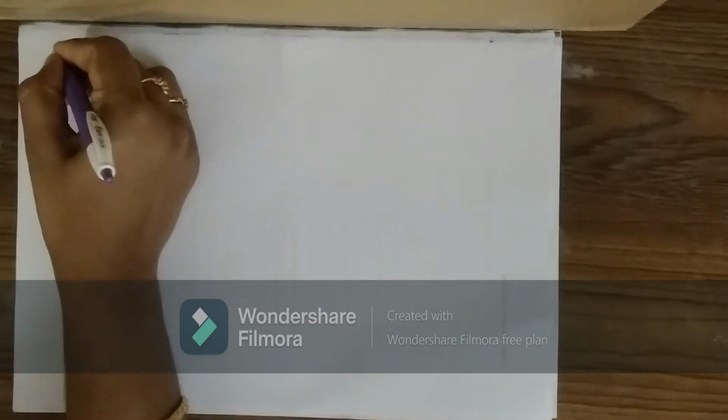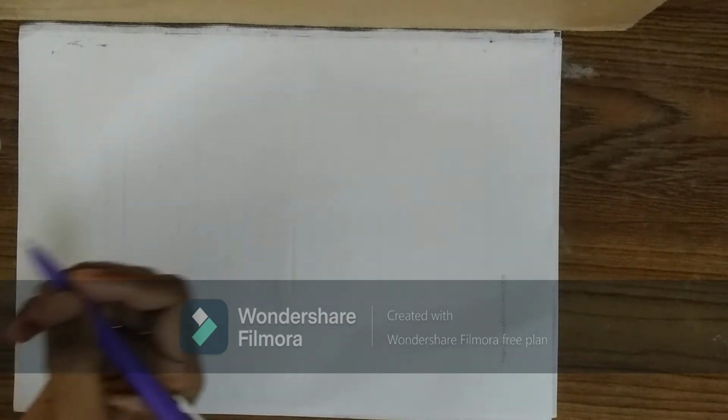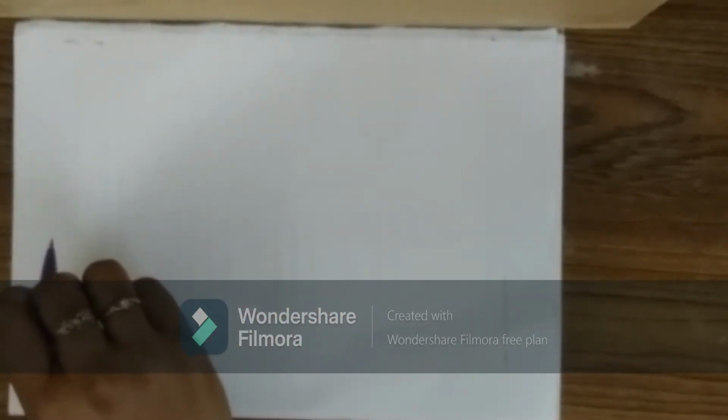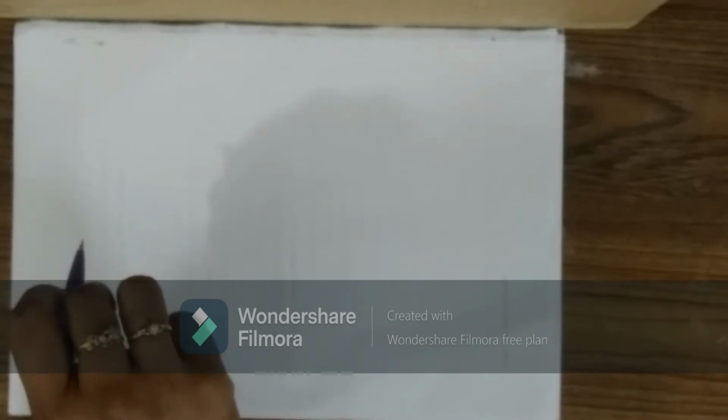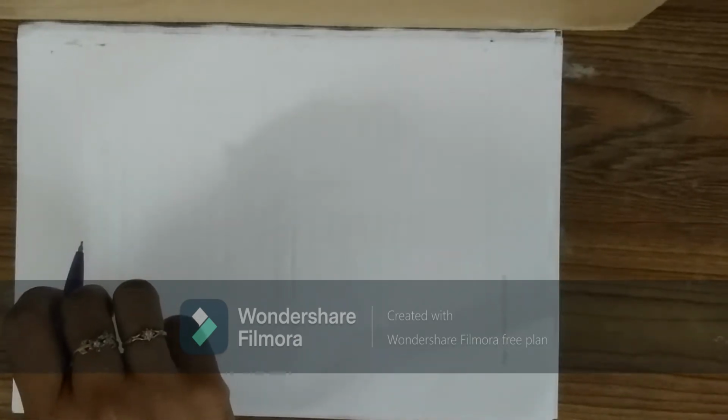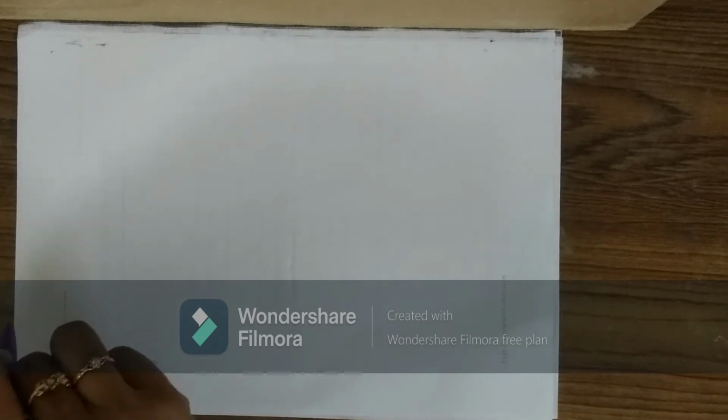Examples of active components, as I told you, are voltage sources, current sources, generators, transistors, diodes. Examples of passive components are resistors, inductors, capacitors, and also transformers. Transformers are used to step up or step down the voltage. The power and the energy remain the same. Okay, so a transformer is a passive device, a passive component.